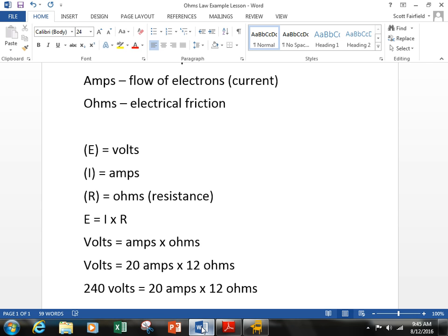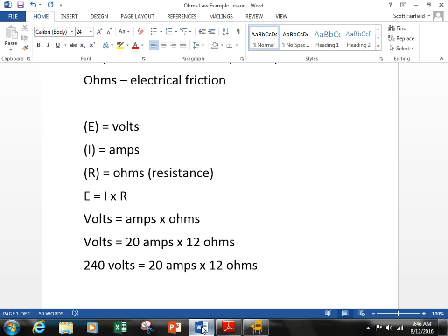And the reason why we need such a thing is your electrical wires, your devices are rated at certain power loads and amps. The wires are rated like this, so the electrician's got to make sure whatever's on the circuit, the wire has the capacity, or what we call ampacity, to carry the load and not overheat and not burn the house down. And your circuit breakers match what your wires can carry, because if your circuit breaker is too small, we're going to trip too soon. Or if the circuit breaker is too big for what the wires can hold, then the wires heat up and melt and the circuit breaker never trips off. So that's why this becomes crucial as far as trying to figure out.